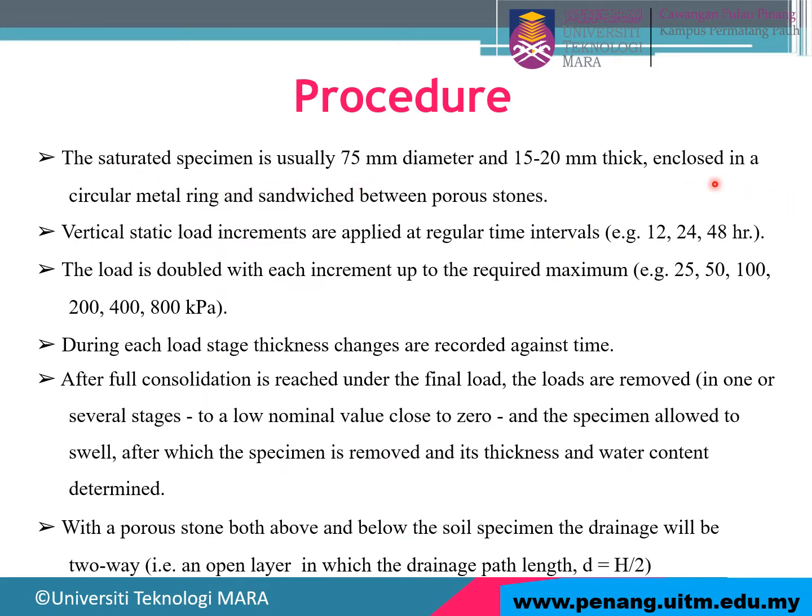It is enclosed in a circular metal ring and sandwiched between porous stone. So it means that we have the sample, and you put the porous stone at the top and the bottom. Vertical static load increments are applied. So just now we applied the load, at regular time intervals of 12, 24, and 48 hours. The load is doubled with each increment up to the required maximum, for example 25, 50, 100, up to 800 kilopascal.